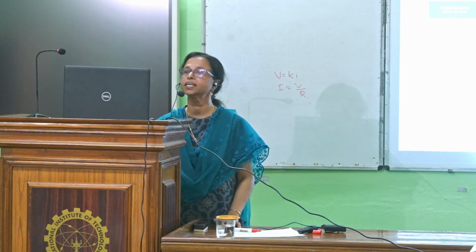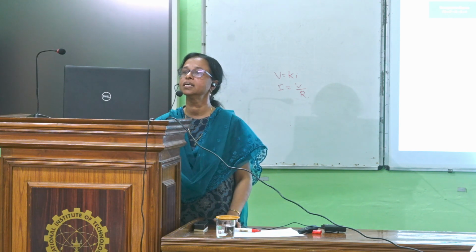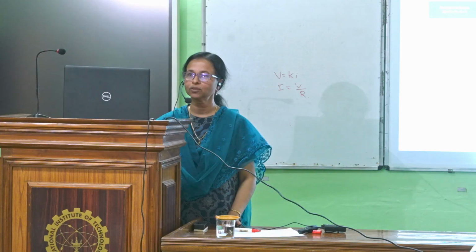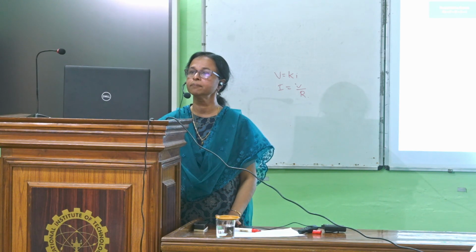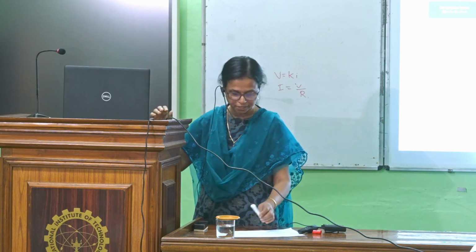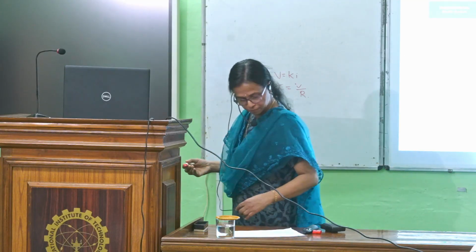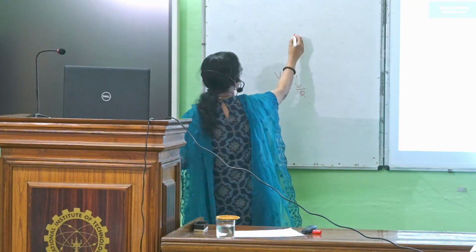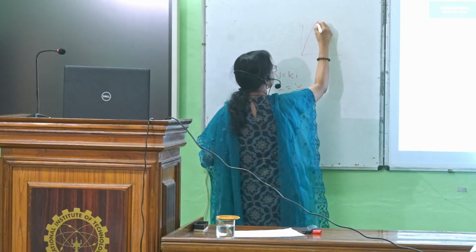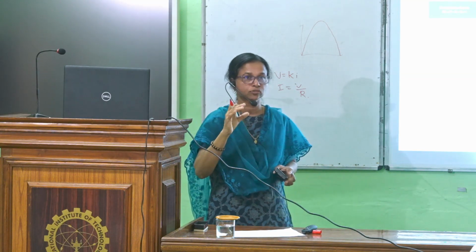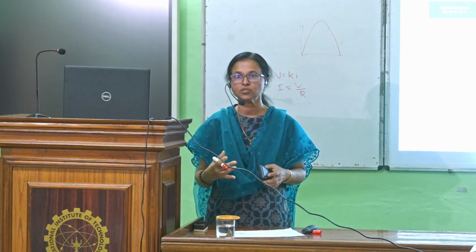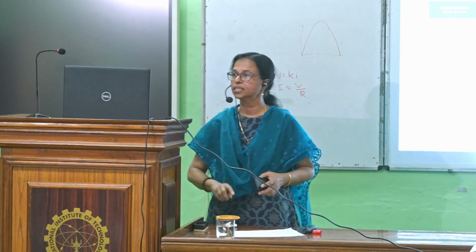So the curve number method is one loss estimation method. Then we can find out what is the excess precipitation, and this excess precipitation is converted into the direct runoff hydrograph. Direct runoff hydrograph means it always starts from 0 and ends at 0. So for a particular hydrograph, you can find out the direct runoff hydrograph. Here the base flow, the groundwater flow, is not included. So finally you have to include the groundwater flow.